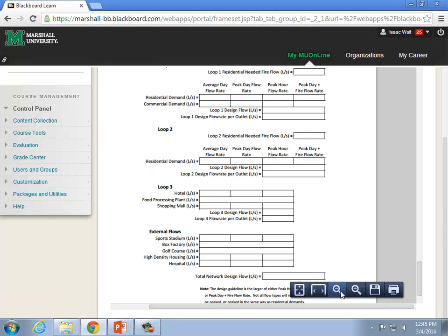No, it's not something that I made up. It's a rule of thumb that's mentioned in Water Resources Engineering by Chin. So it's a real thing, but usually if you were going to do this at a real place, like a town, you'd go to the town next to them and look at their water demand patterns rather than just using a rule of thumb like this to size the pipes. There would be related data somewhere else that you could use to extrapolate. Yeah.